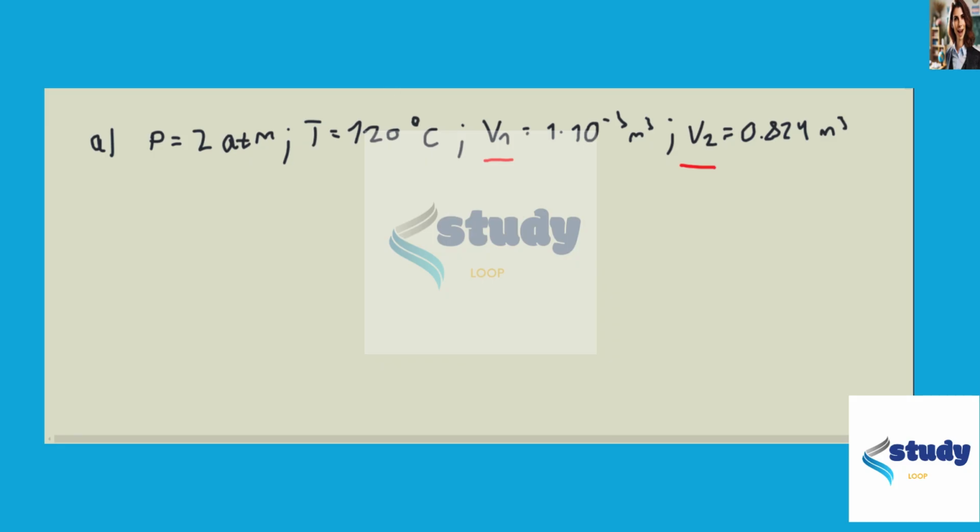So for the part A of this solution, we need to evaluate this work that is being done while the water is being evaporated. So for the total heat of vaporization, the heat of vaporization was given also in the problem. The work done to vaporize the water will be the work done. And here we can use a standard formula for constant pressure work. So at a constant pressure P, the work will be only related to the change of volumes.